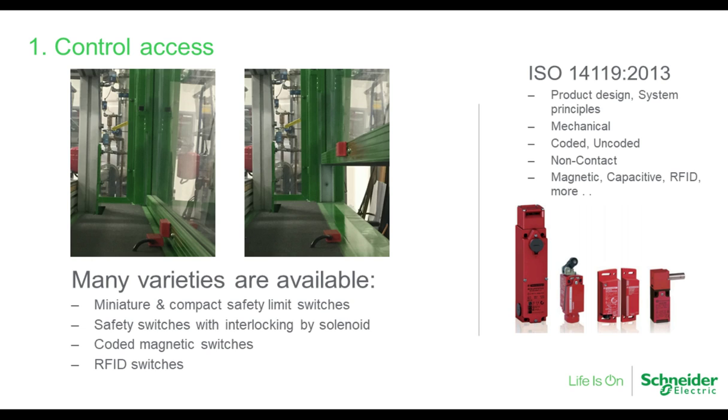But they're also interlocks, so most of them have a way to lock the door, lock the cover, so that it really cannot be opened while the machine is running. So they serve both of those purposes and help to prevent accidental restart, and really to help enforce properly accessing the hazardous area, making it easy.